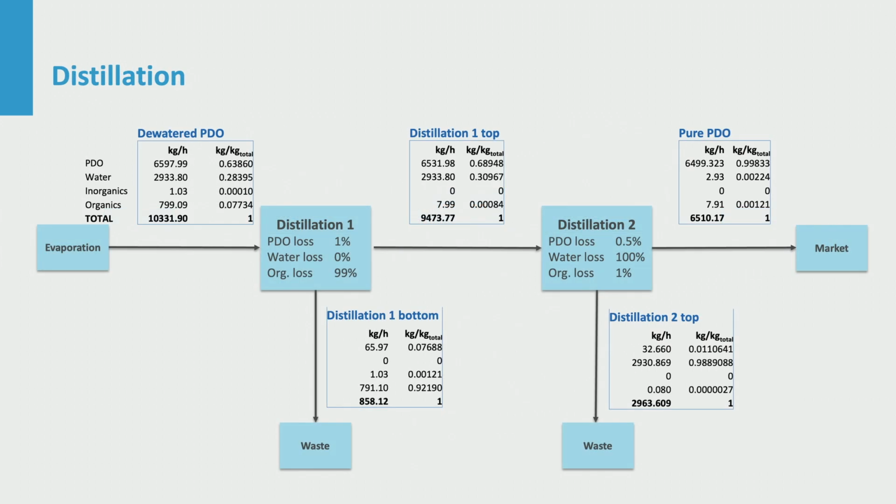To design the distillation train, we would have to specify the organics in detail and their volatilities. Then computation of distillation can be done using complicated but well-developed and reliable methods. For now, we first distill PDO over the top to remove higher boiling components, and we then distill out lower boiling components. We hope that no close boiling impurities were around or have been formed by degradation during distillation. Without performing detailed design, we can still guess split factors per distillation and review the mass balances that we obtain.